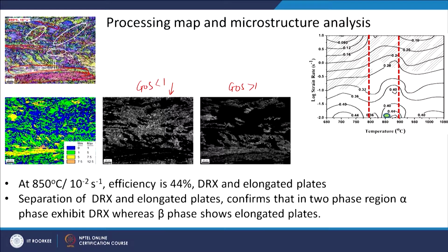During the transformation they will have some kind of martensitic transformation, whereas alpha, because it is already alpha, cannot have a transformation. So, these grains are not showing any plate type of formation, but all these big grains are showing formation of martensitic plates. So, through that you can say that these big grains are from beta grains and all these very fine recrystallized grains are from alpha phase.